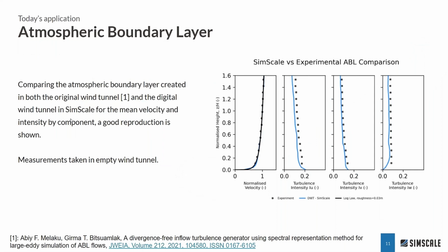So what we show here, first of all, we need to ensure that the wind profile that we're getting out of this virtual wind tunnel with all these roughness elements and so on is actually the same as you would have with the other alternatives. So the analytical target profile for the atmospheric boundary layer, which we see here in the left, following this logarithmic profile, and with the black squares, the results that we would get with an experimental wind tunnel. So here we can see that for the mean values, we exactly match the reference.